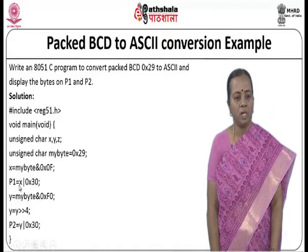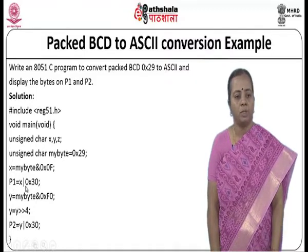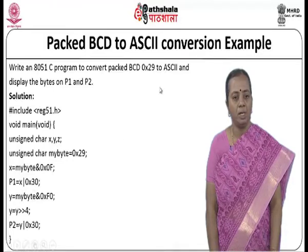Now, P1 is equal to the x value which is 9, ORed with hexadecimal 30. So, now these two are added together, so that I will be getting a value of 39 at P1. So, I will be in a position to get that 39 is the ASCII number for BCD 9, which we have simulated. We wanted to convert this BCD to ASCII. So, 9 is converted into 39 now, which has been placed at P1.